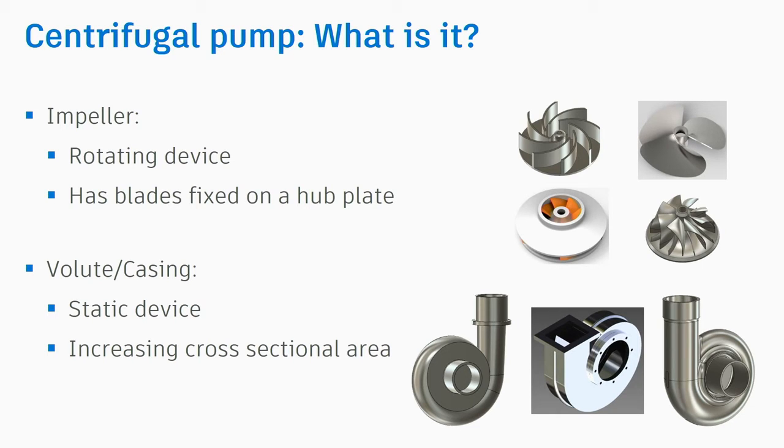Each one of these components has different designs, geometries, and shapes. In CFD, you can play with them. You can juggle between the different geometries, combine them, and then run them at the same time, and then decide what is the best performing model. And if you are running on the cloud, you should be able to run 20 simulations at the same time and get the results.